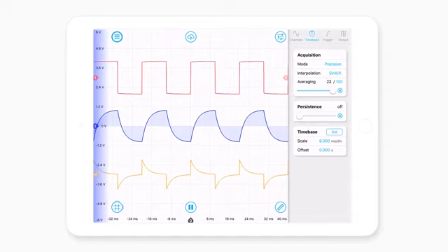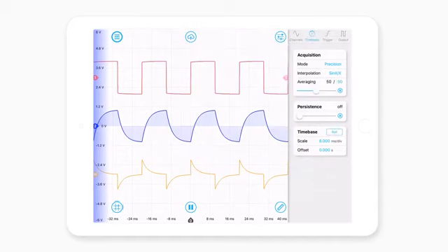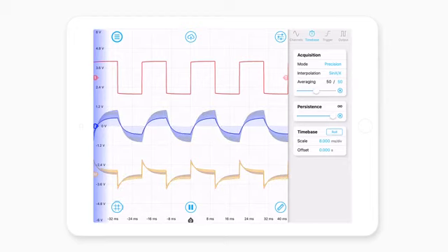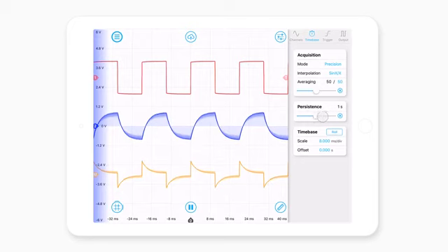And you'll see here that as more frames become available, the oscilloscope is averaging over them collectively, up to 100 frames. If I wanted to set something very specific, I can tap the blue text and say I want to average for 50 of them. Then there are things like persistence. This is interesting. If you want to see how your signal is changing over time, you can set the persistence anywhere from off to 1 second, 3 seconds, up to infinity, essentially.